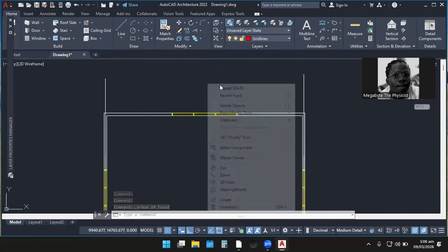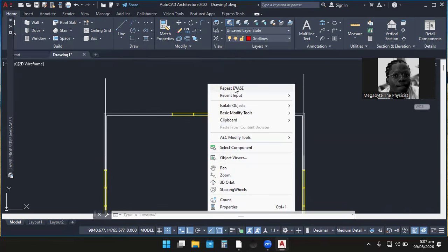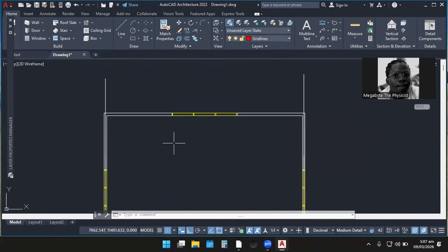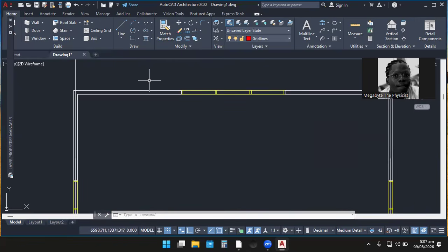So let's quickly get an offset for this other dimension too, and let's proceed. So let's offset 150. If the whole dimension is 12,000, let's get the first one. So this over here, let's offset inward. I'm done selecting, so I've clicked the offset. After offset, let's specify the distance, and let's use a distance of 75. If we like, we can use a distance of 450. Then we offset this one.